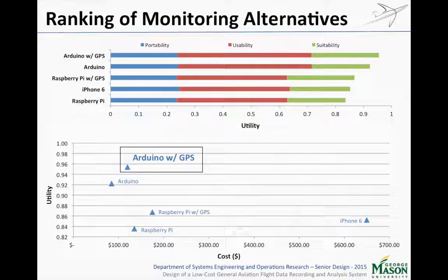And so we learned from that prototype and realized that if we wanted to prototype again, the Arduino Mega would be a much better platform, because the Arduino Mega has 4 times the random access memory as the Arduino Uno, costs only a few dollars more, and based on the amount of memory that we need to use, the Arduino Mega should work.